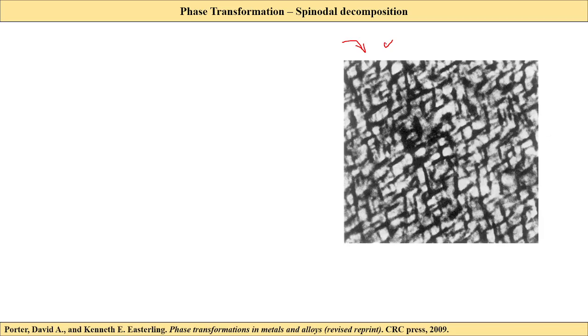For example, if alpha 1 has 40% copper and 60% nickel, then alpha 2 has quite opposite percentages, 60% copper and 40% nickel. I'm just taking this as an example. From BSE imaging you can directly see the richer phase appearing brighter, because the signal coming from that phase will be higher.